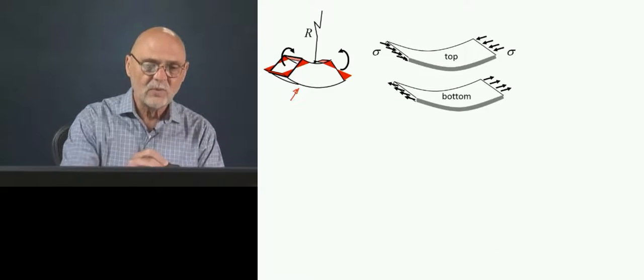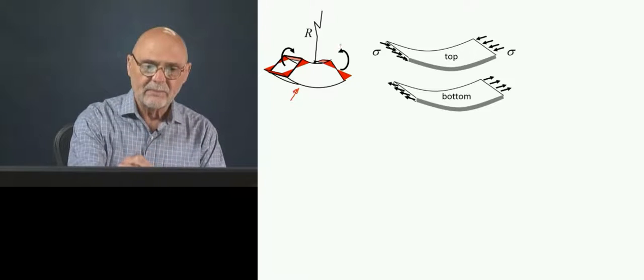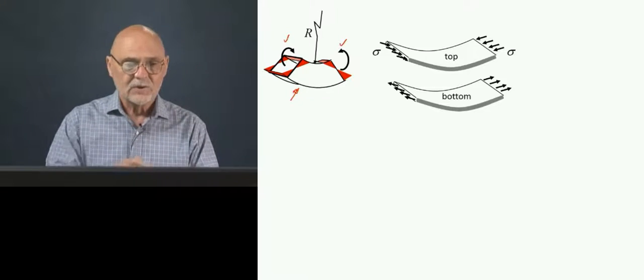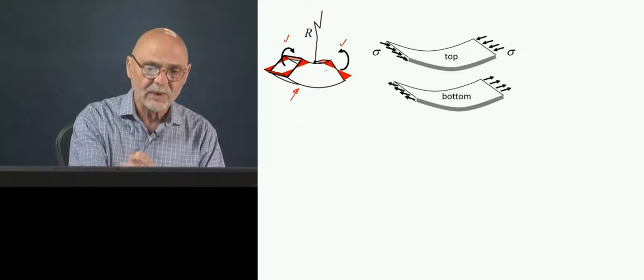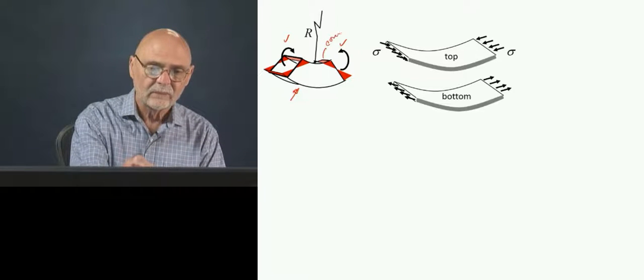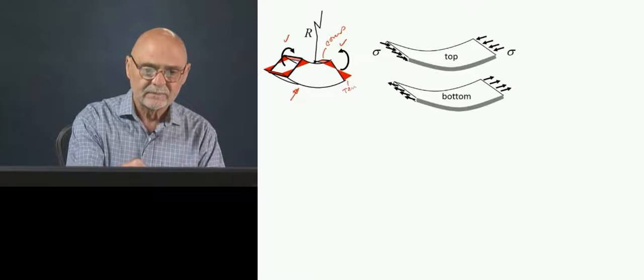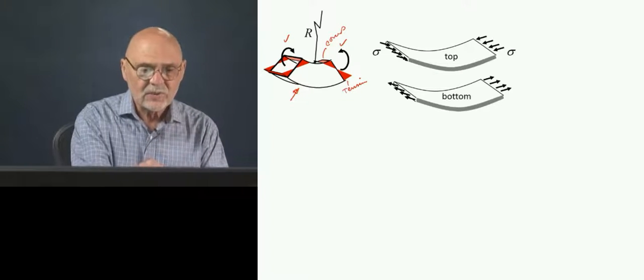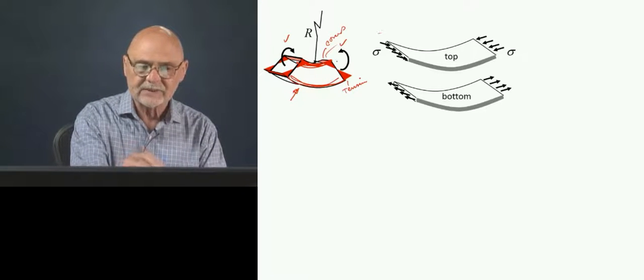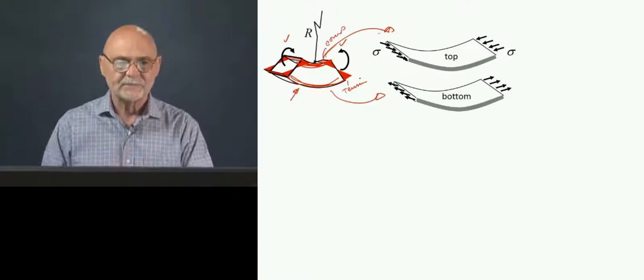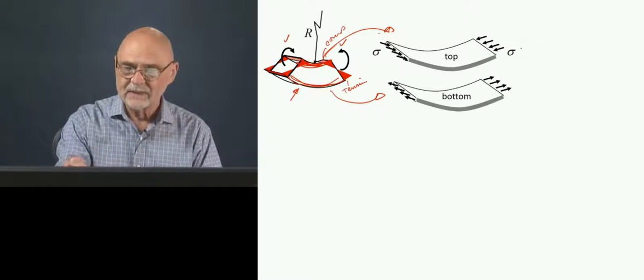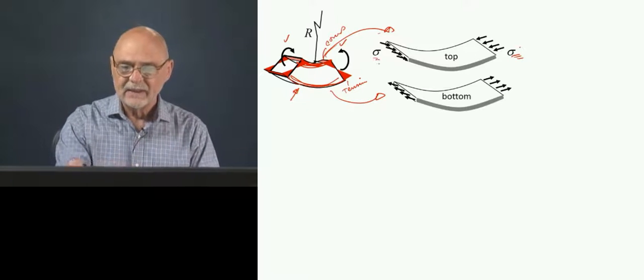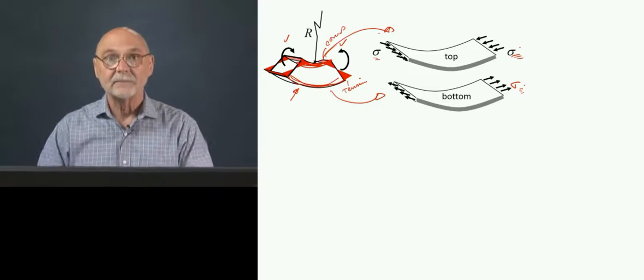So here is a thin wall section applying a bending moment at either end, so that the stress distribution is going to be compressive at the top and tension at the bottom. Again, this is thin wall, so this is a hollow section. If we break out this top part, just one metal thickness, and the bottom part, it will look like this, and the bottom like that. So we have this compressive sigma at the top and a tensile sigma at the bottom.